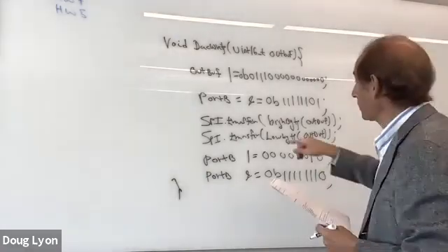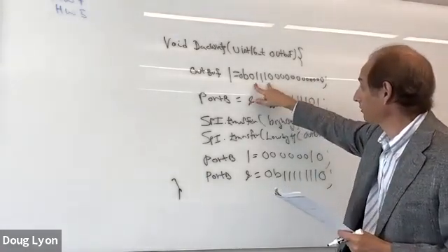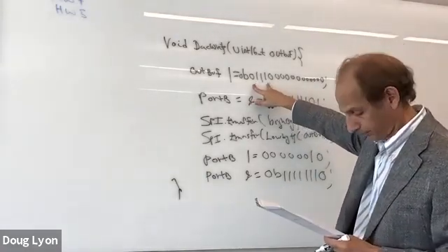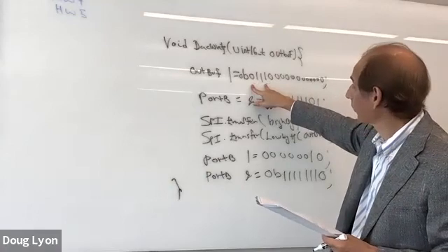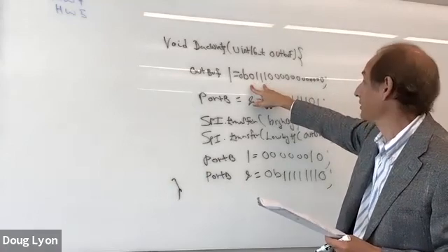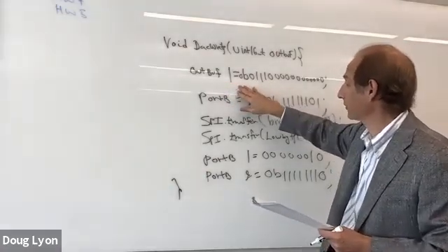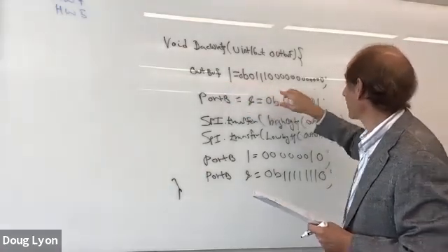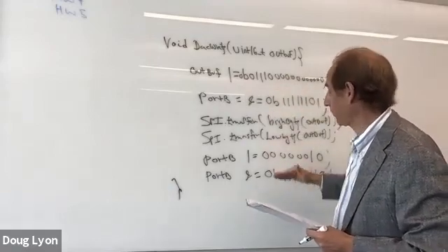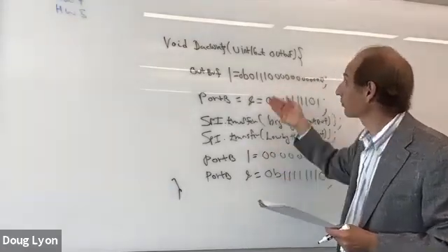So what does this do over here? It sets the 3 most significant bits, right? And that is the answer to question 18. And we kind of saw this at the beginning of the talk, but now we can see where it's actually being used for the bit flipping for us to write a device driver for our little DAC.